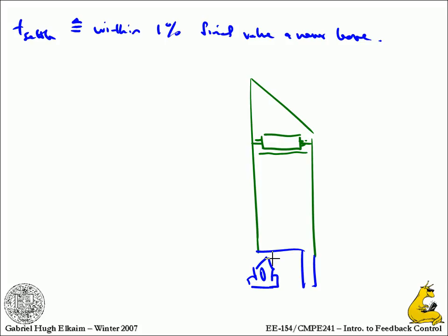Because of this, it's got 3 legs, but it doesn't have the 4th one. And these are relatively spindly legs for such a big building on top of them. So they've got this big thing that shakes it back and forth, more for wind loads than anything else. They try to keep the building perfectly vertical, so when the wind comes along and wants to bend it, it shakes its way back to center.